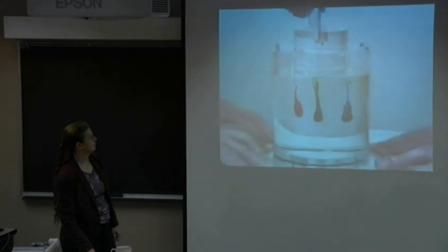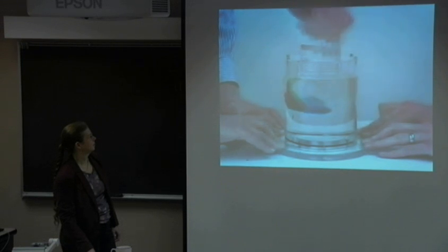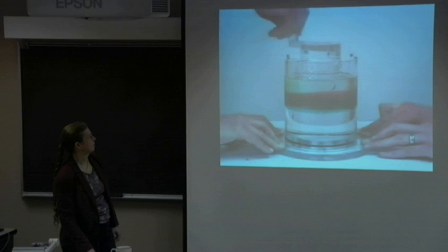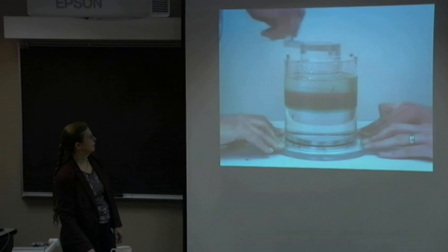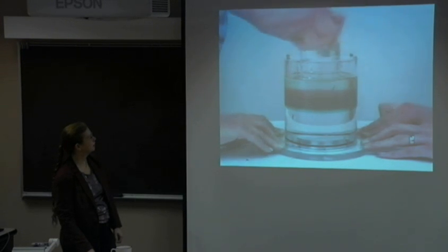All right, now we're going to rotate these fairly slowly, 5 times. Notice the flow is laminar because the Reynolds number is less than 1. Reynolds number measures how streamlined it is. And he's going slowly to avoid turbulence. And he's using corn syrup because it's viscous, so it'll be less likely to be turbulent. 4. 5. Now we're going to go back.